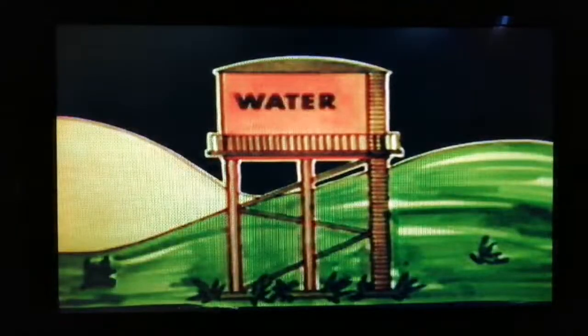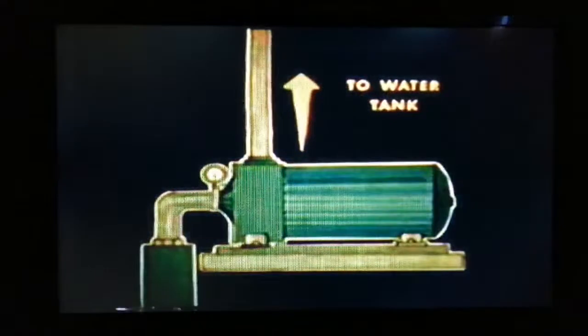This air, under pressure, may pass through another cooling section, or aftercooler, and is then fed into a storage tank called a receiver. The receiver acts much like a water tower. Here, a large quantity of water is instantly available as needed. With such a reserve storage system, the size of the required pump can usually be a great deal smaller than would be necessary if the pump had to supply the demand directly.